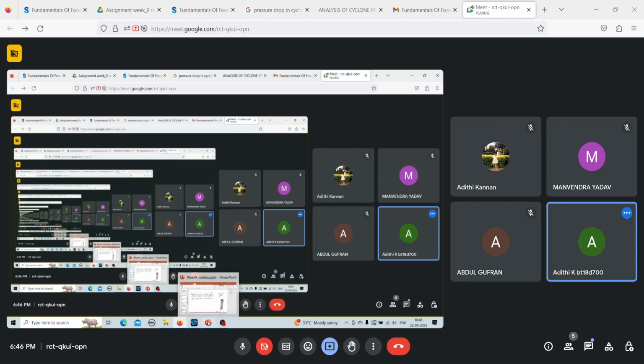Diameter is given, we convert it into radius, which is 12 centimeter, so I am substituting it in meters as 0.12. So acceleration is given, everything else is given, you need to find n. But the value of n you will get will be in revolutions per second. The question is asked in revolutions per minute, so we will convert it later.